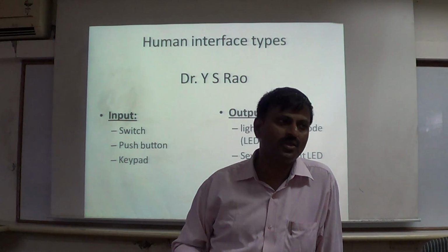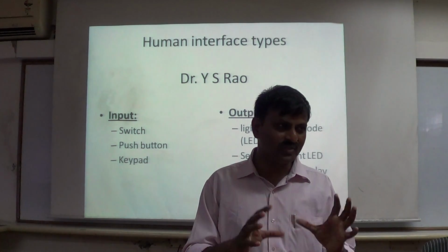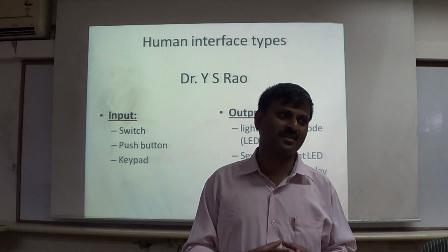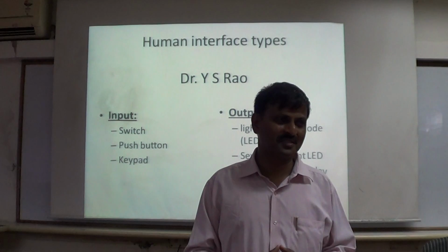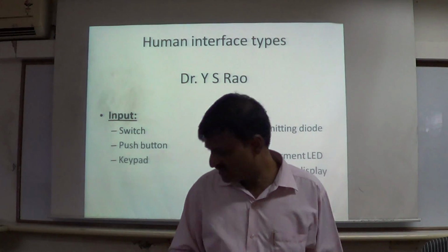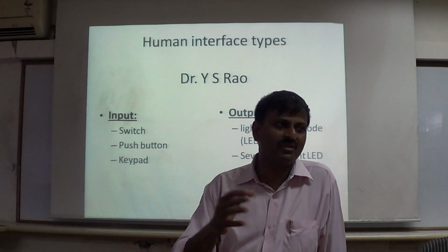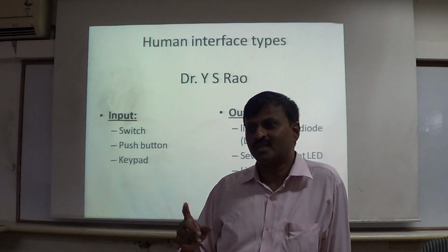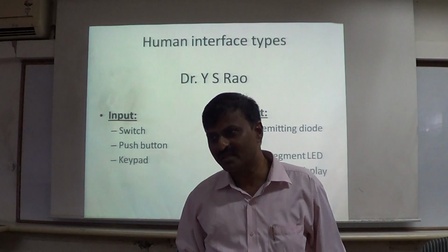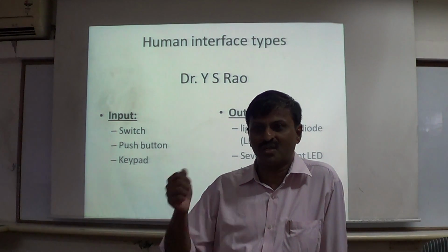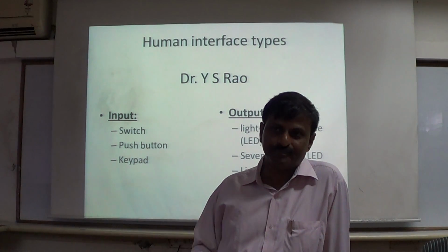Okay, so that is why I said, when you say robotics, it's not only just controlling the motor. It also deals with this gear arrangement: how you convert this motion into its corresponding displacement by properly mounting the gears. You will have to reduce the torque on the motor finally.